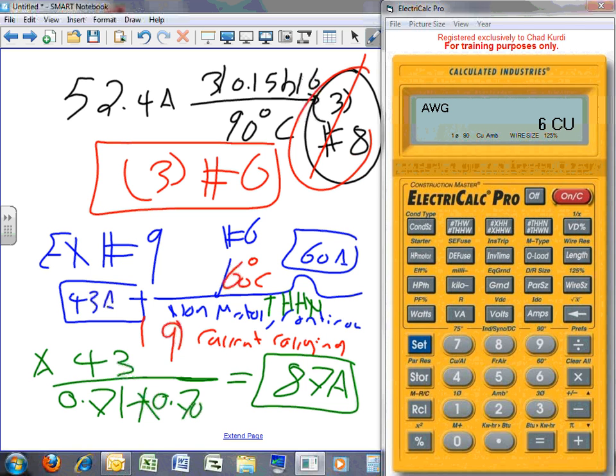Up to this point, everybody should know how to do that, guys, when you're derating. That's not a new topic for you. You take the two factors. Engineers and designers look at the load, not the conductor. You don't find a conductor to guarantee how much current I can pull out of this. You always start with the load. I know when we teach you guys derating, probably with Gary and elsewhere, they derate this conductor to this and that. But we don't have the conductor; we are creating the conductor. So we always start with the load, and instead of going right to left, we go left to right with the sizing. Same method.